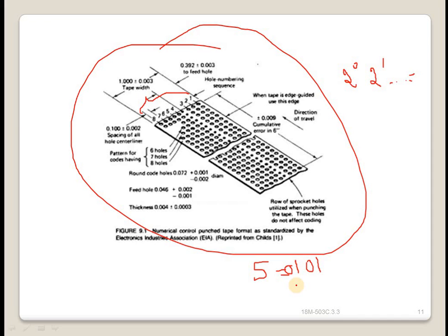In a 2-axis system, only 2 of the words would be used. In a 4 or 5-axis machine, additional A words and B words would specify the angular positions. Although different NC systems use different formats for expressing a coordinate, for example X 7.235, Y 0.5, some formats do not use the decimal point in writing the coordinate. The plus sign to indicate a positive coordinate location is optional. The negative sign is of course mandatory.